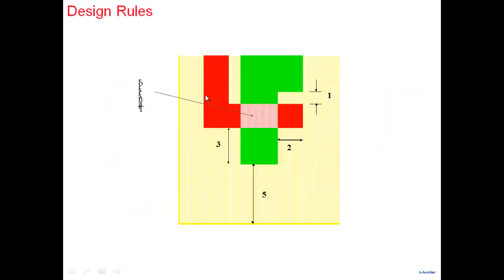And so this is the rule for making a transistor. Note that this region is N plus, as I showed in the last lecture also, and this region is poly. And wherever the N plus and the poly intersect, this is where you get a transistor. Now, the rule says the following: the poly that you see here must extend beyond the N plus region by at least 2 lambda. See, you want the transistor only till here, right? So normally you would think, well, let me bring the poly only till this particular point, and that's it, stop. But what is the design rule saying? Well, you have to take the poly and extend it beyond by at least 2 lambda.